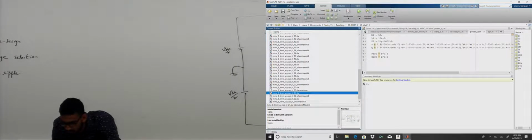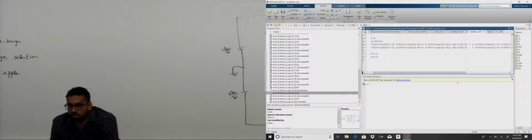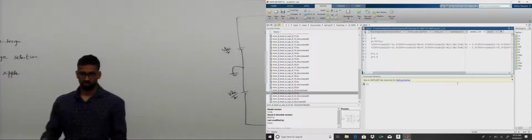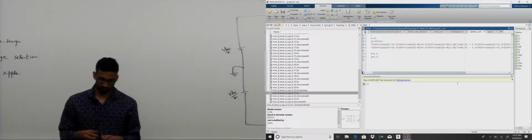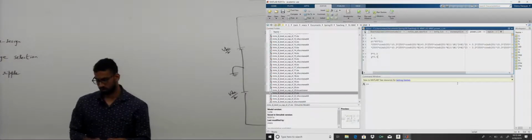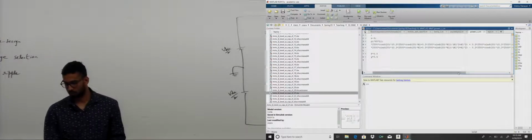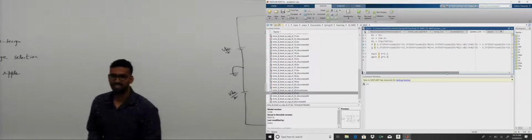P is this. So m cos alpha is a variable, m sin alpha is another variable. You solve these two equations for m sin alpha and m cos alpha, and you get m and alpha. So you can only get P and Q for solutions of those two equations. Yes, correct. So the P and Q we can select are restricted, so that they get solved by these two equations. So 5000 watts and 400 VAR is possible.